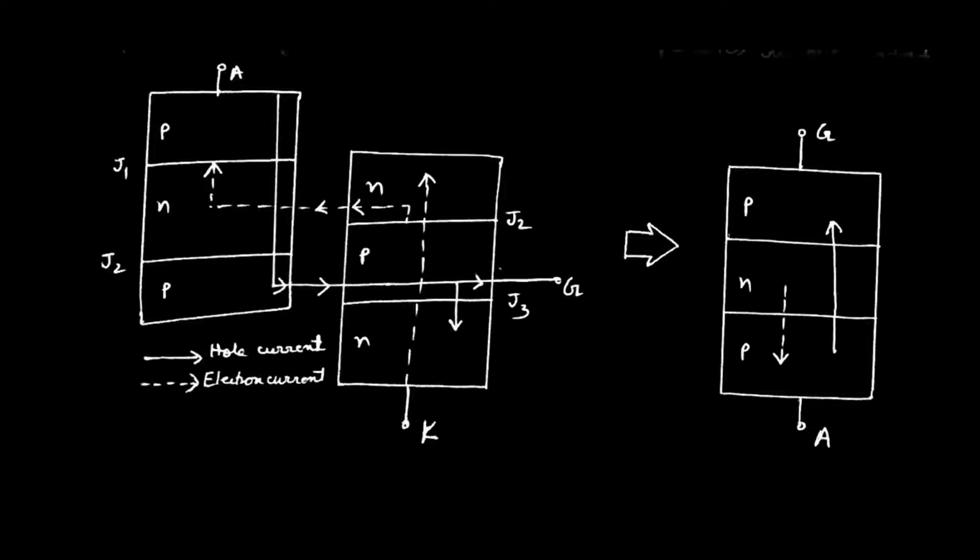Now, the question is the working principle. Similar to a thyristor, the GTO can be divided into two complementary connected transistors, p+np and np+n, that is reflected in this figure, in which the straight line gives us the direction of the hole current and the dotted line gives us the direction of the electron current.